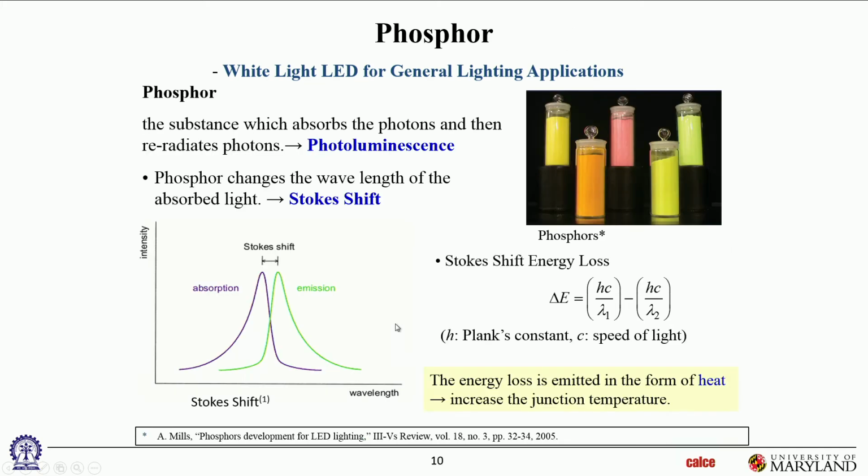So that's what it's doing. It's absorbing blue light and then emitting light that looks much whiter, and that shift in frequency of the emission compared to the absorption of the phosphor is usually called the Stokes shift. But again, there are losses in that process. You can see there are energy losses, an efficiency loss for that part of the process also.